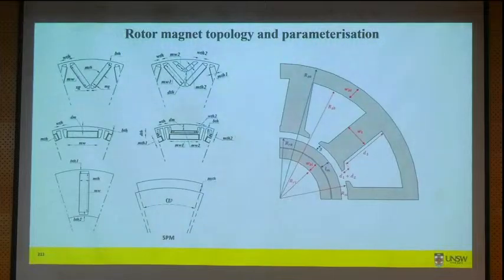And then the rotor geometry. For IPMSM, we have so many different types, right? So here you are seeing a few that we discussed previously. V-type, double V-type, conventional flat type, double layer flat type, spoke type, or SPM. Okay? So these are our options. And out of these, we could check each one of them during optimization to see which one will be best suitable for achieving the objective. Okay?